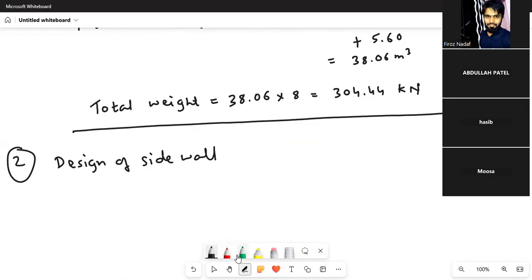Okay. So horizontal pressure, you know how to find the horizontal pressure from Rankine's formula. We know that horizontal pressure PH equal to gamma H into cos square phi. Here H is H2. Remember, whatever H2 we have gotten, that is H here.